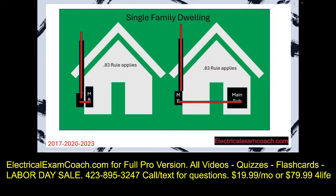And the scenario on the right, for all of that wire there for the service itself, and then also for the main feeder, as long as that panel that it's feeding is feeding the entire structure. You would go to that table, do your cheat sheet, find your size breaker, slide over, and you'd be able to use that size wire.